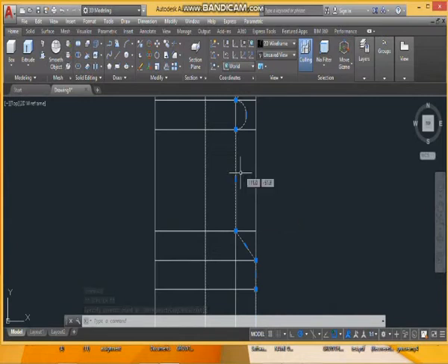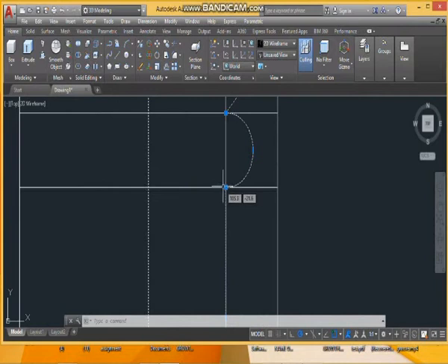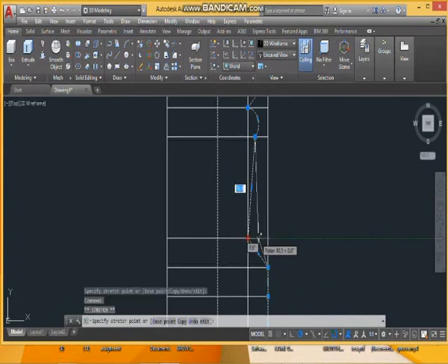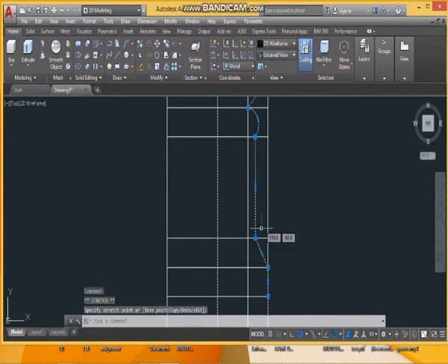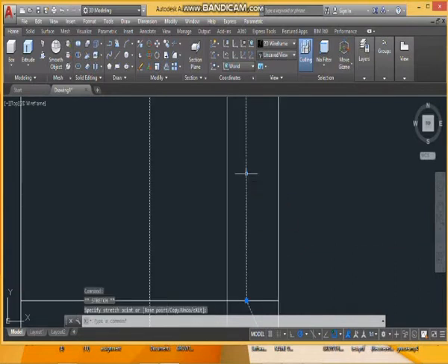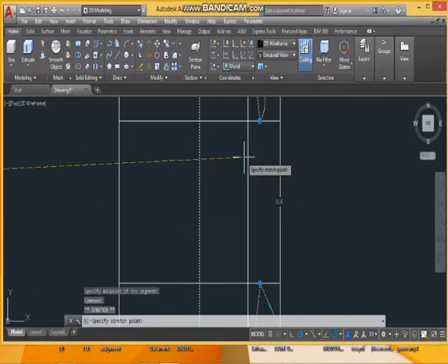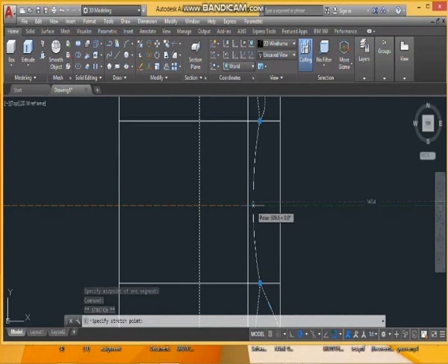Yes, we convert. When you take your cursor to a summit, it gives you options. You don't need to click. You take your cursor carefully to one of the options and you click before you go on. Like here, there are 3 options. We're going to select convert to arc. Click, then you adjust where the arc is. Sometimes it becomes very large, we don't know why, so you have to click and bring it closer to where you actually want it to be.